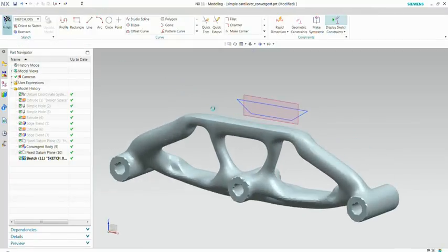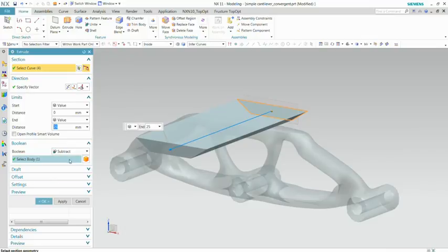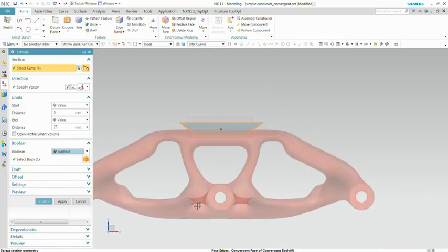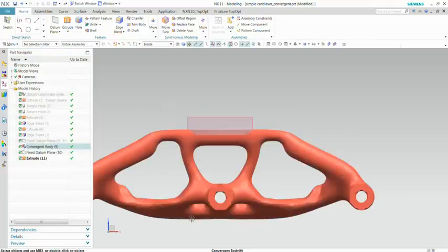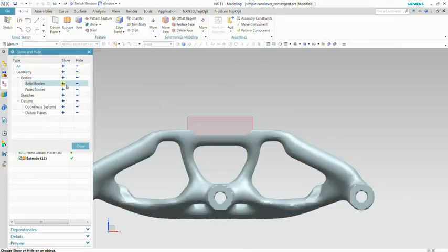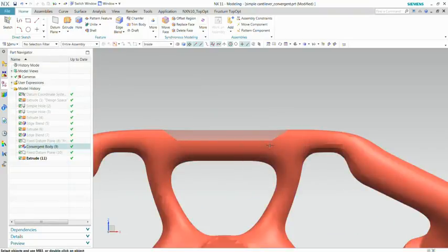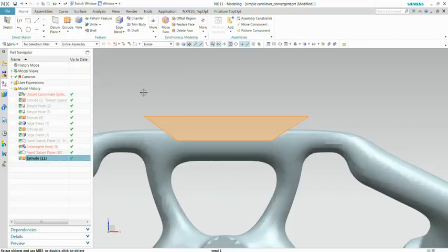So I'm defining this shape, and when we say that we can combine it with faceted models, I can subtract, for example, this shape from this part. And as you can see, let me just hide the data plane. We just created in this faceted model a cut out using a classical modeling operator and this shape.